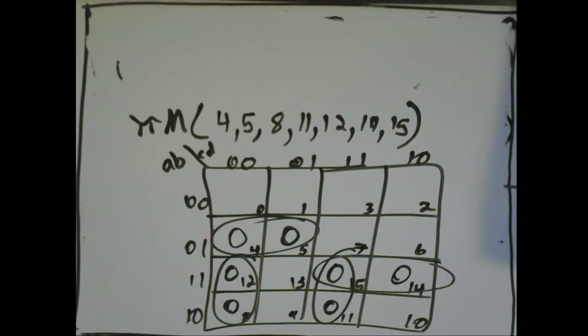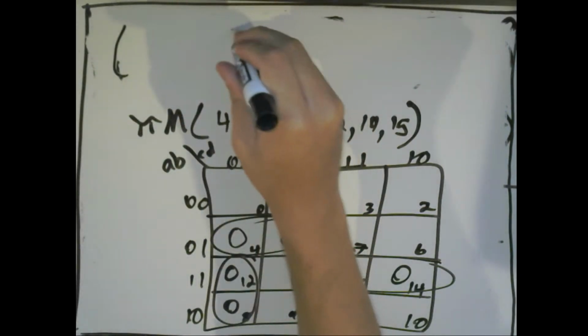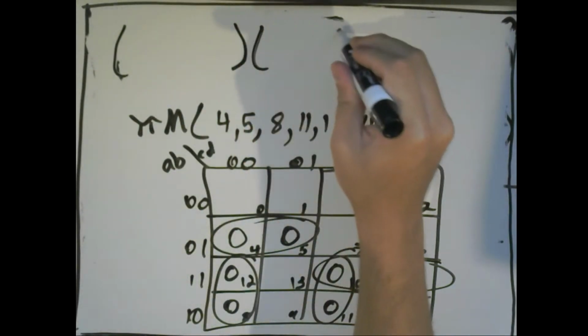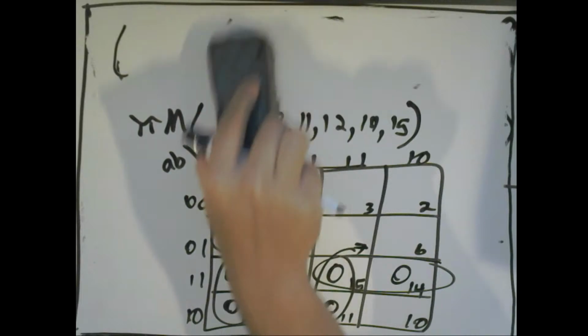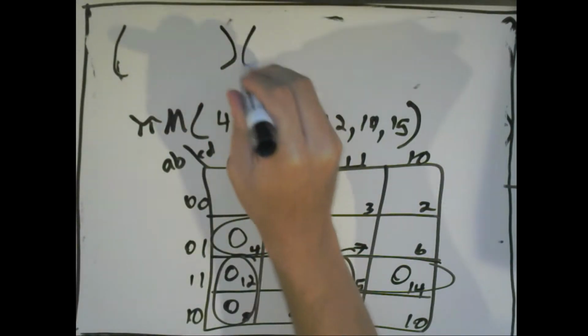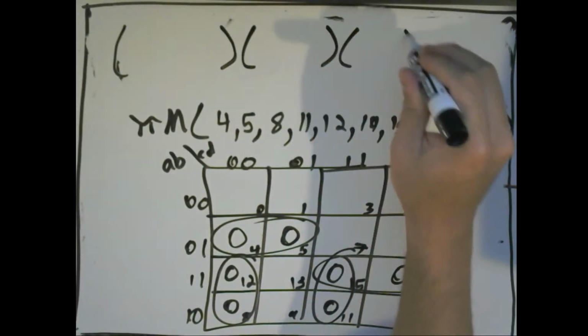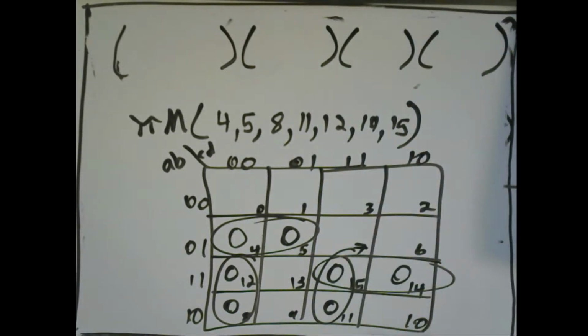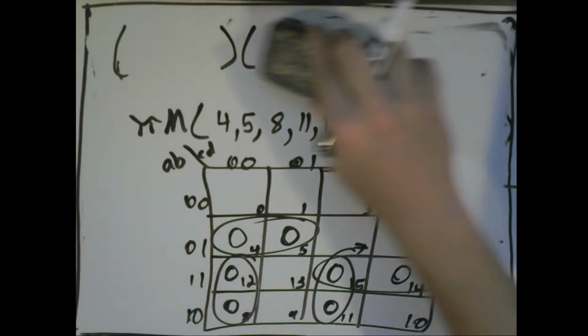We're going to do the same process here, but it's kind of backwards because of how the POS works. So let's start creating terms here. I'm going to end up with 4 equations since I have 4 prime implicants. Might run out of room here. Change these up.